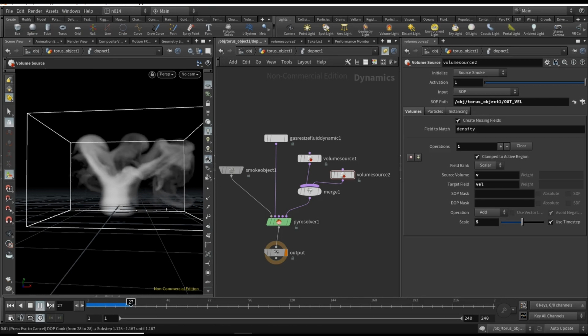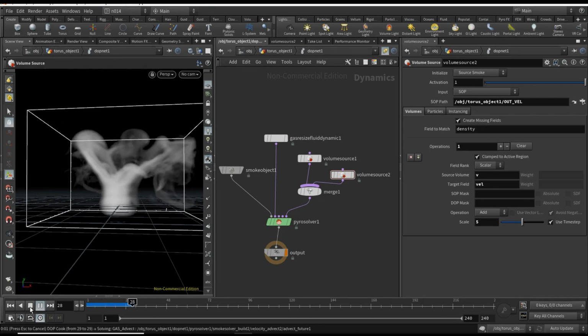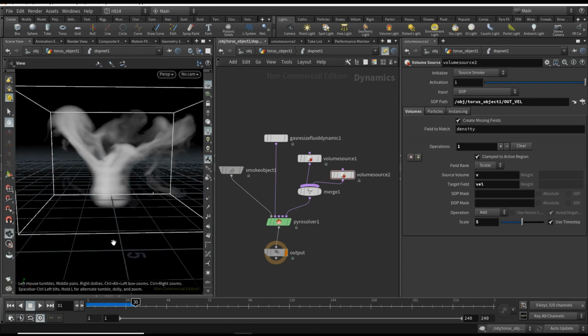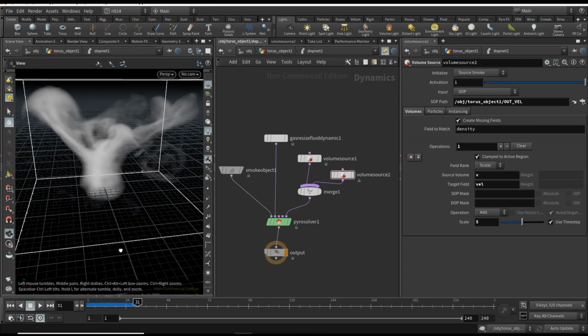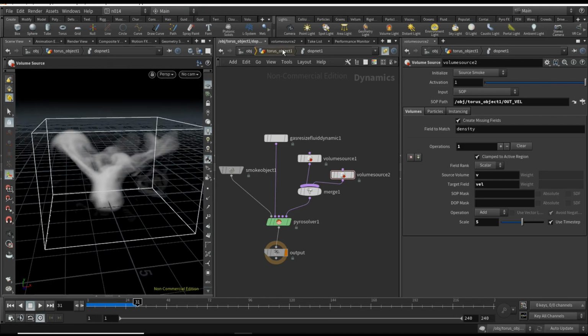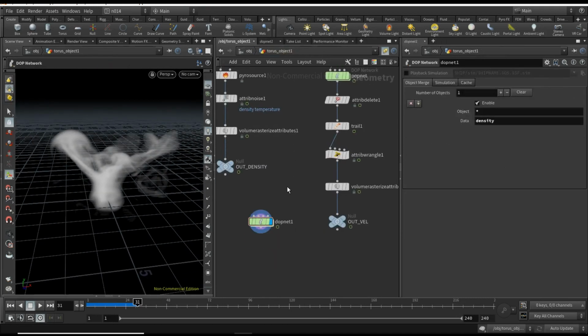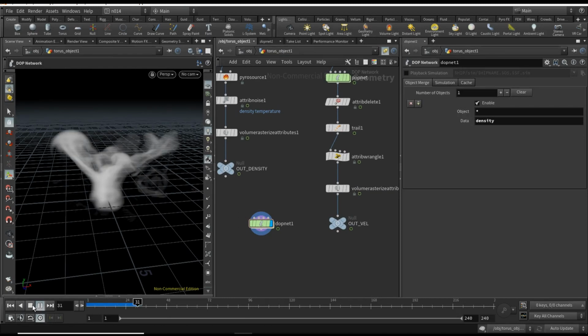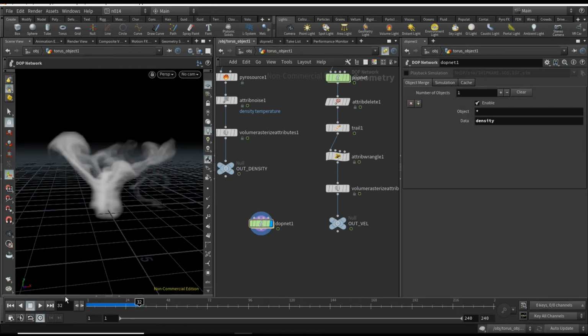However, one thing you might have noticed, for some of the voxels density has appeared, but the particles animating might still not have reached there, or simply the particles might not have been birthed yet. So density has appeared but no velocity to guide it. There might actually be much more happening inside Houdini, but we can assume this way.